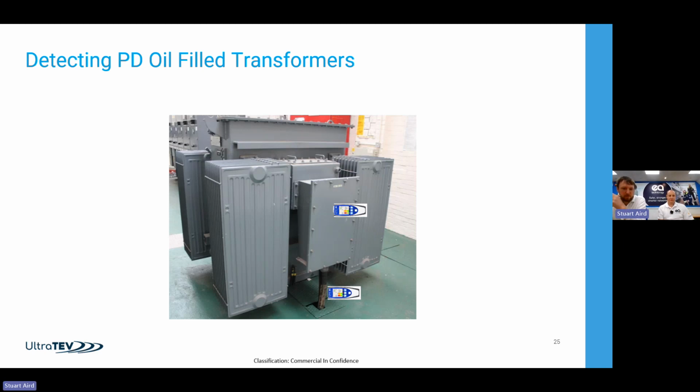Additionally, for the air-filled cable boxes, we want to try and get an air path in there to see if there's any termination activity, any surface activity. Quite often these are vents on the base up around the bottom of the cable, where you can get a clear air path in. Or in the case of a sealed box, we use our contact probe, which allows us to pick up the ultrasonic activity, so that's surface type discharge, through the skin of the metalwork. Not a preferred option, as there's obviously an attenuation path in that, but as you'll see in a minute, it does work, and you can see inside that sealed box.